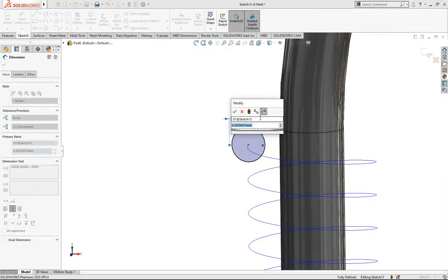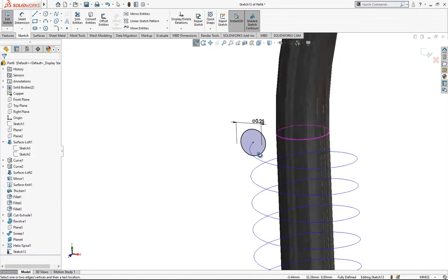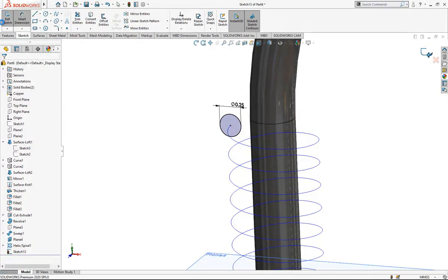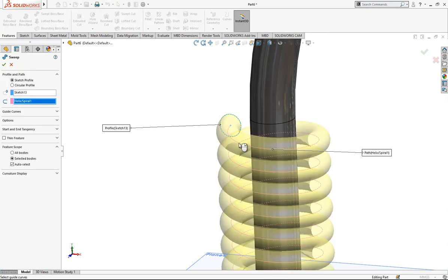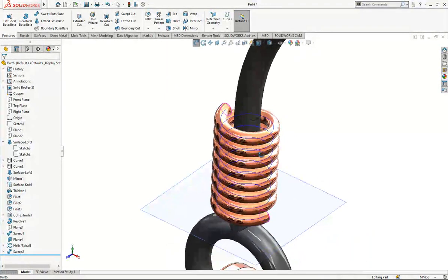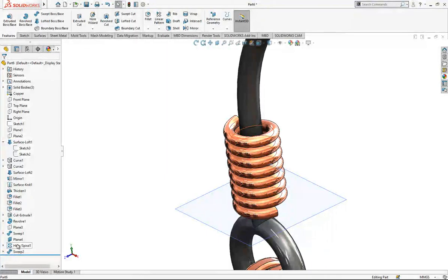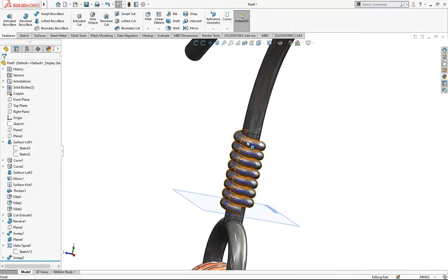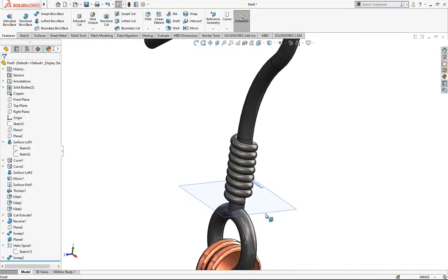Here we make our radius value 0.249, because if I make it 0.25, because the pitch is also 0.25, this operation will fail, because there will be zero thickness between two objects, and the program will not be able to handle that. And as you see, it is looking a little bit bigger. And now we go to the helix, and the operation which we use for creating the helix circle will be 0.65, and let's see what the result is. Yes, something like this we were looking for, and you can add additional radii on it.